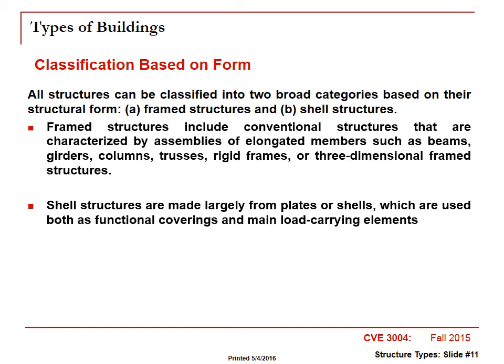Frames are not just beams. Frames can be made up of trusses as well, rigid frames, space frames, and so on. That's not the only type of building that you have. That's the most common. You can get into buildings that deal with shell type elements, which are plate type elements that resist vertical or lateral loadings. Probably more specialized than what we see 99% of the time, but still can be used for building type.